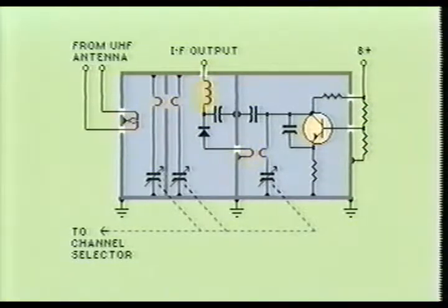The result of the combined signals is the difference frequencies which are outputted through the UHF intermediate frequency output connecting point. The 2 IF frequencies at the output of the mixer stage are 45.75 MHz for the picture carrier and 41.25 MHz for the sound carrier.